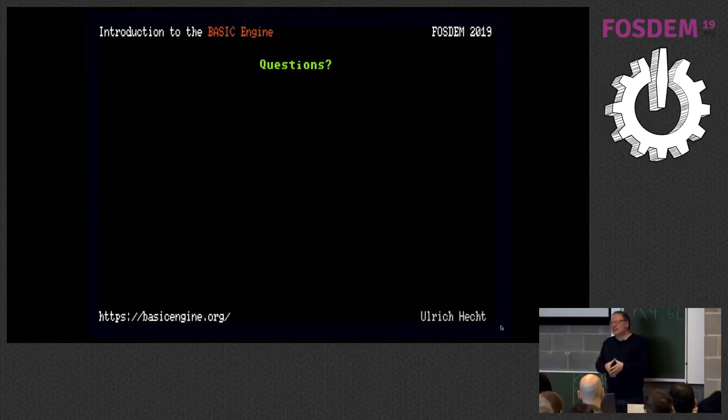Not a really digital output. With this hardware you can't, because the chip only produces composite video. VLSI has made a new chip that is basically 4 of these concatenated, and with this you could produce a VGA signal. So that is probably the best you can do with this kind of stuff.